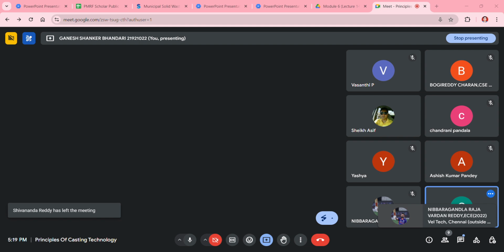The capacity is 6 and utilization is 0.67. So 230 divided by 6 into 0.67, that utilization factor. So the number of containers will come to around 57. Then you just have to divide 57 by 11, because in one trip you are collecting 11 containers. So it is five trips per week only.